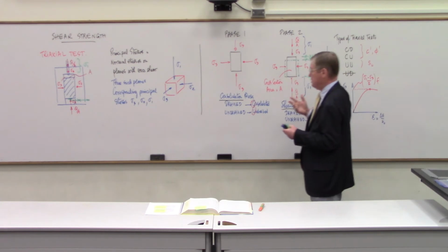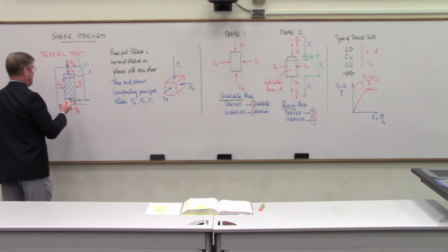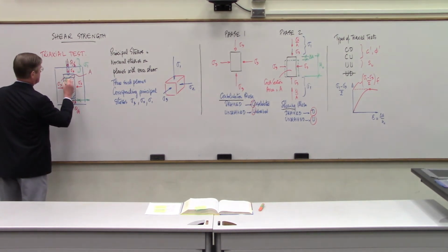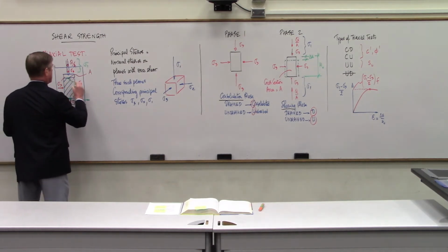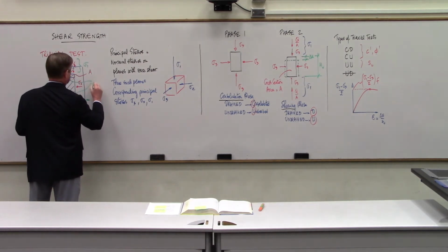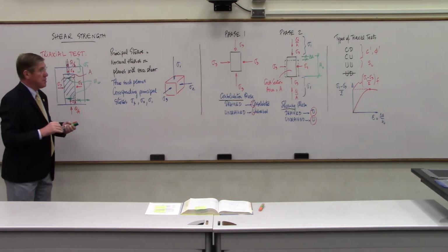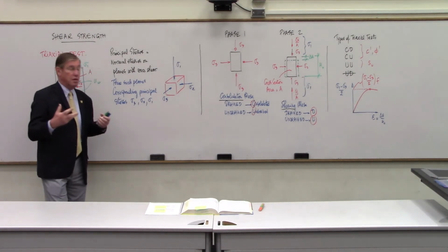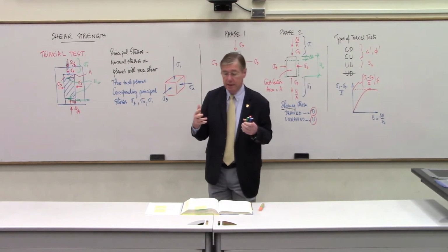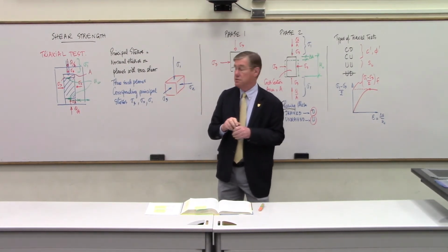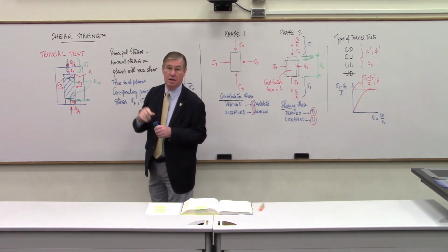triaxial test. In addition to this, in this triaxial test, we can make some pore water pressure measurements. Typically we can put a sensor here, we put a sensor there. So right here, if needed, we can measure UW. That's a big advantage because if you want to obtain the effective stress, sigma minus UW if it's saturated, or sigma minus alpha UW if it's unsaturated, then when you measure this, you can actually obtain the effective